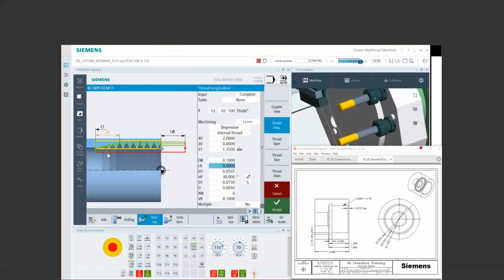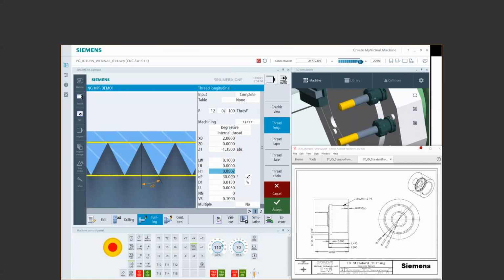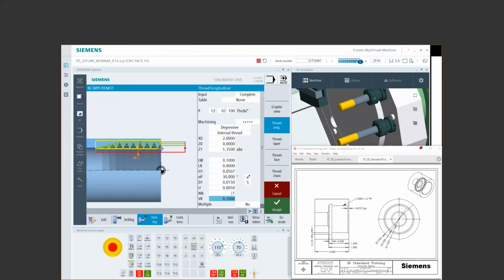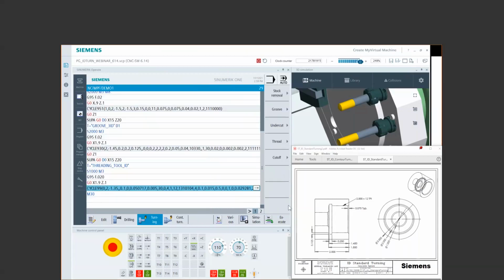I can do a lead out, but if you leave it at 0, it should do a rapid retract out. Thread height, angle, all the normal stuff you would set up for a thread. Maybe I want to do a little spring cut. Once you define the threading cycle and drop it in, now it's really about done with the job. So I am going to, again, get in that habit of doing a retract. Now at this point, I may want to shut my spindle off, shut my coolant off. I'm probably going to want to do our safety retract.